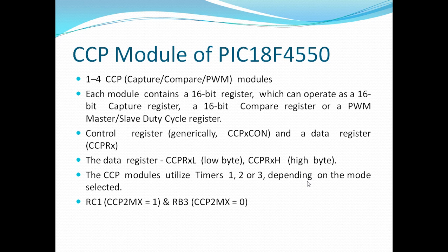All these CCP modules have registers for capture and compare mode. Timer 1 and timer 3 are used for those, and for PWM mode timer 2 is used.